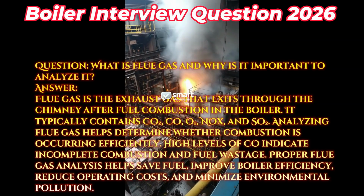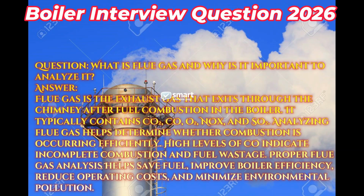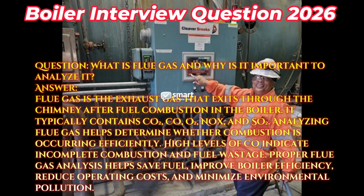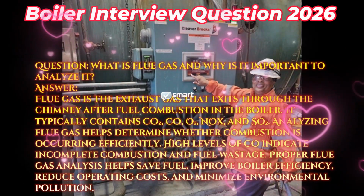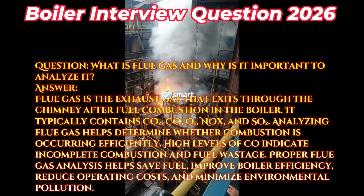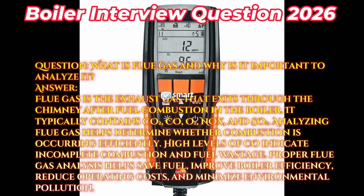Question: What is flue gas and why is it important to analyze it? Answer: Flue gas is the exhaust gas that exits through the chimney after fuel combustion in the boiler. Typically contains CO2, CO, O2, NOx, and SO2. Analyzing flue gas helps determine whether combustion is occurring efficiently. High levels of CO indicate incomplete combustion and fuel wastage. Proper flue gas analysis helps save fuel, improve boiler efficiency, reduce operating costs, and minimize environmental pollution.